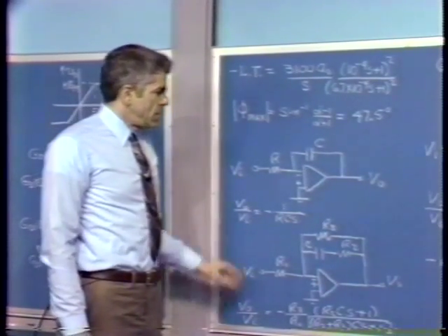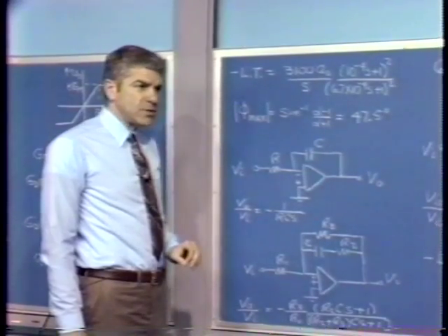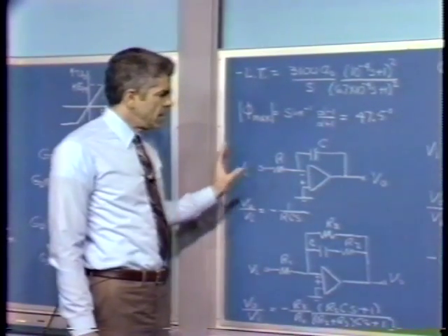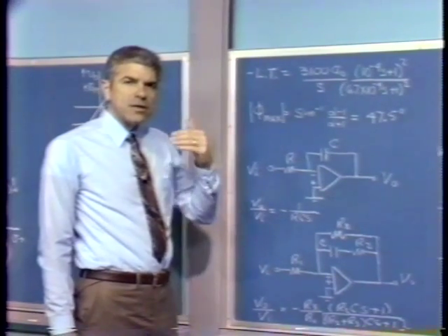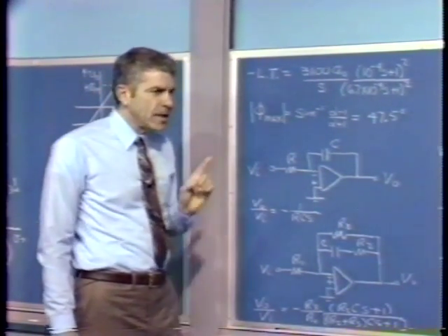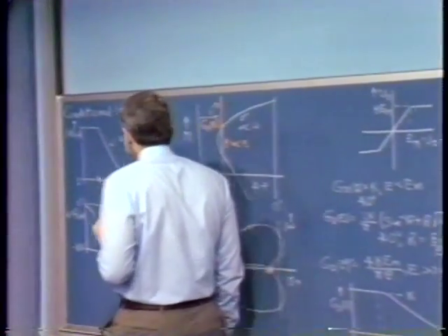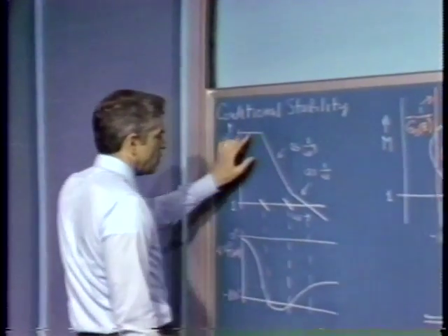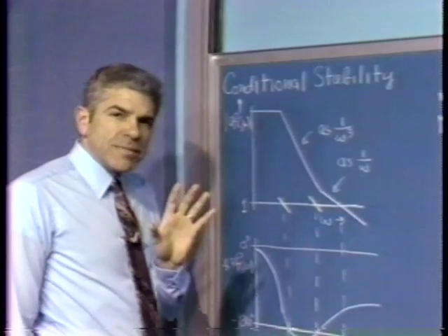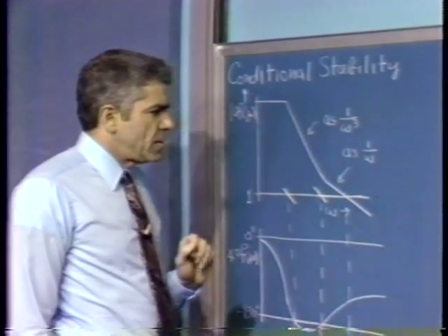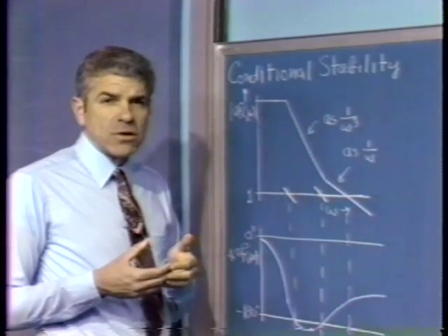In order to implement a system like this, we've simply built it up out of operational amplifiers, but it's not a completely made-up system. The way you get into this sort of a thing, the reason that you get into this problem typically is as follows. Let's look back at our original frequency or magnitude versus frequency curve. When we look at a typical feedback system, there's usually some process that limits the maximum achievable crossover frequency.